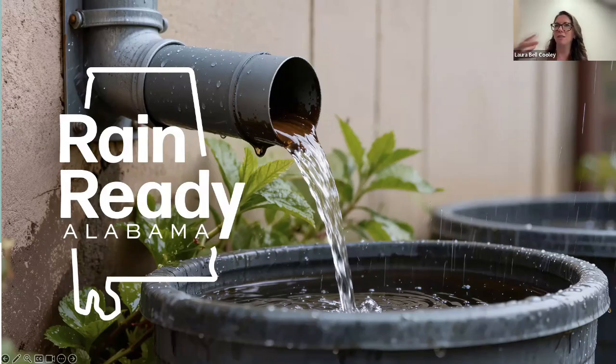So it could be helpful at the front area where that amount of water is entering the waterway. But I think using native plants along your stream bank as a stabilizer, you're going to have better results over the long term, because those natural root systems are going to be much better at actually holding that in place. Whereas riprap can actually cause more erosion over time because it doesn't actually hold that stream bank in place. Does that make sense? Mike, you might do a better job of explaining why that is.